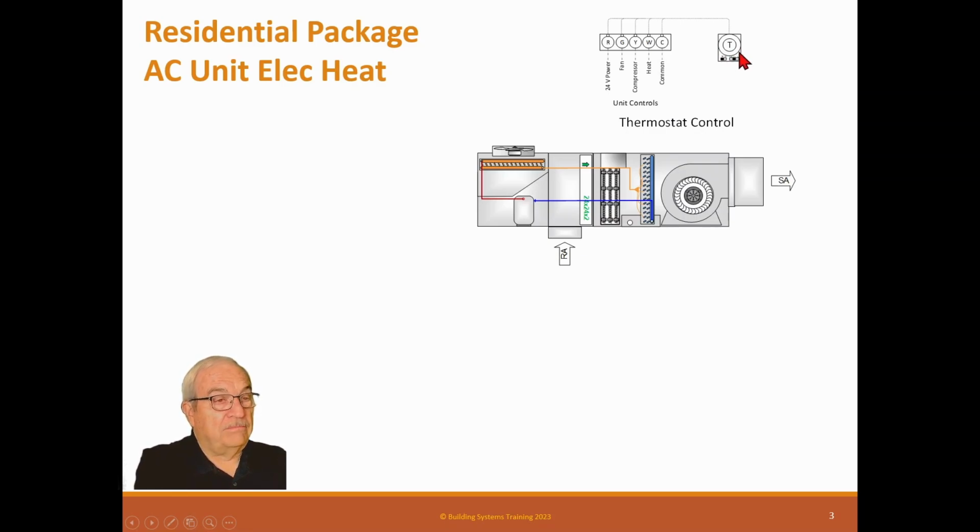See, a regular, normal old thermostat that just had a bimetal contactor or a mercury contactor in there didn't use any power. It just runs the power through it. So if the unit's giving you 24 volts here, it goes through the thermostat, the switch makes its contact, it comes back and starts the fan and the compressor. So that's the way those work. And so this is a standard connector into the package unit.